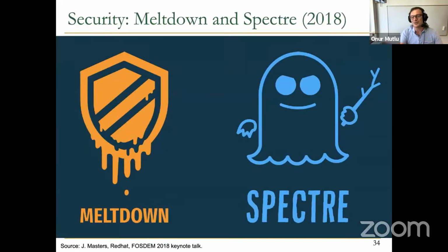Okay, so I'm not going to talk about Meltdown and Spectre as much. How many people have heard about Meltdown and Spectre? I assume many more, because these were publicized quite heavily. But these are essentially issues at the microarchitectural level. Because of the design of the microarchitecture, your system is also vulnerable to leakage of information. This is a bit different from RowHammer. RowHammer is really a bit flip, right? It's a fault attack. But these are more side channel attacks.